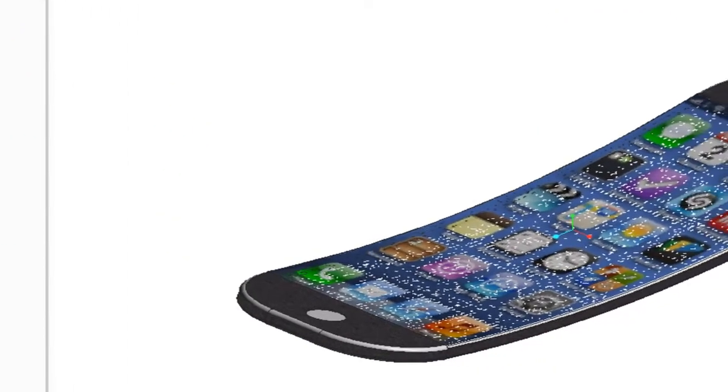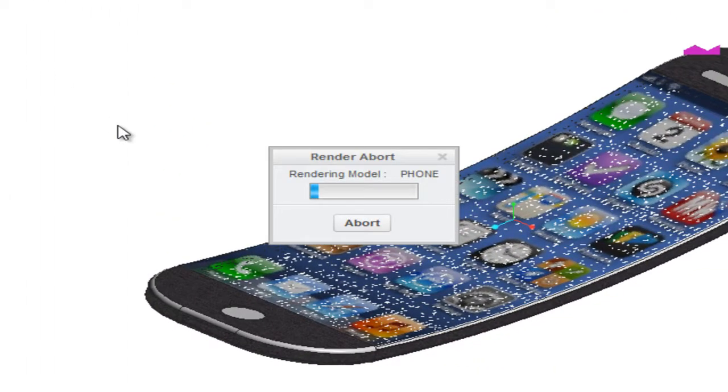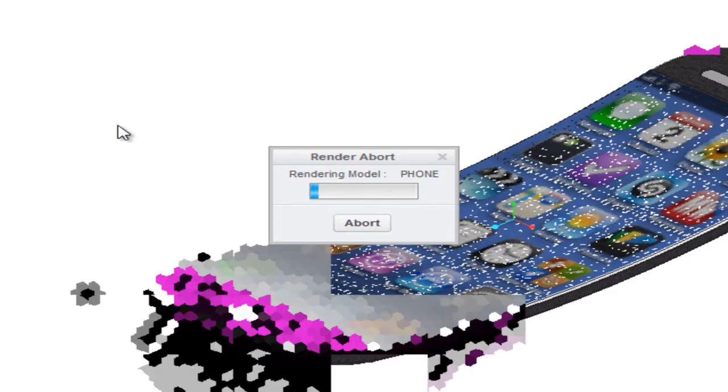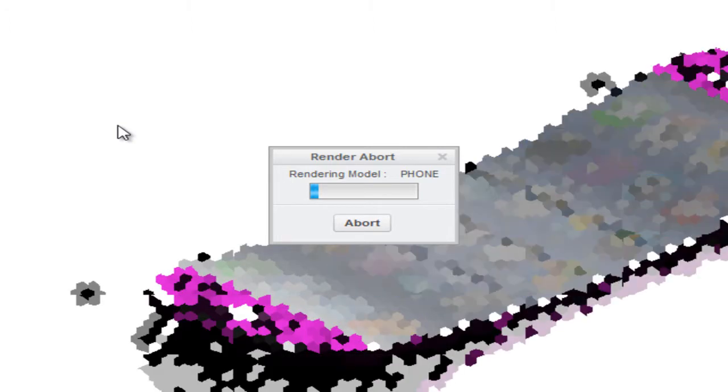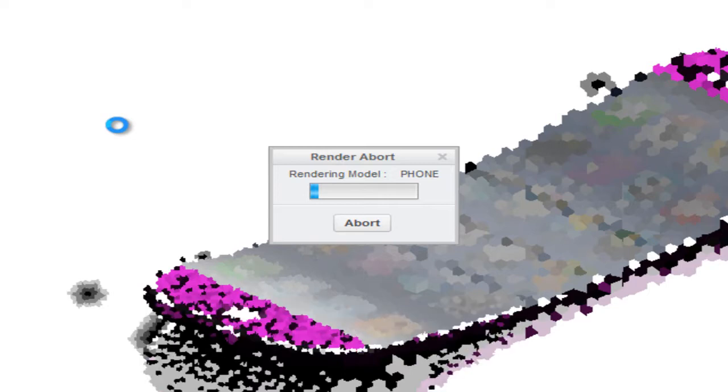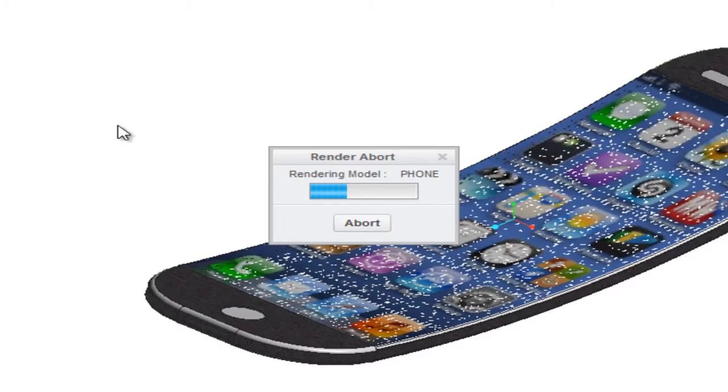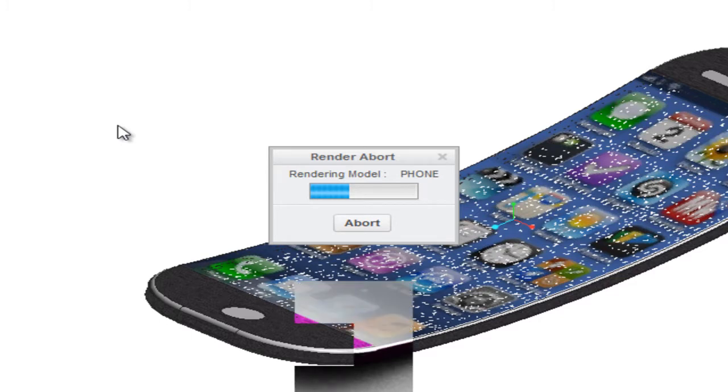And again, hit render. And that will then create the pink phone with that little bit of silver, just highlight it, and then we've got the screen in the middle there. And that's basically how you do it. Now, one more thing I just want to show you once this is rendering is the quickest way to take the image off of Creo would be just to press screen print and paste it into your coursework or into PowerPoint, Publisher, whatever you're doing your coursework in.